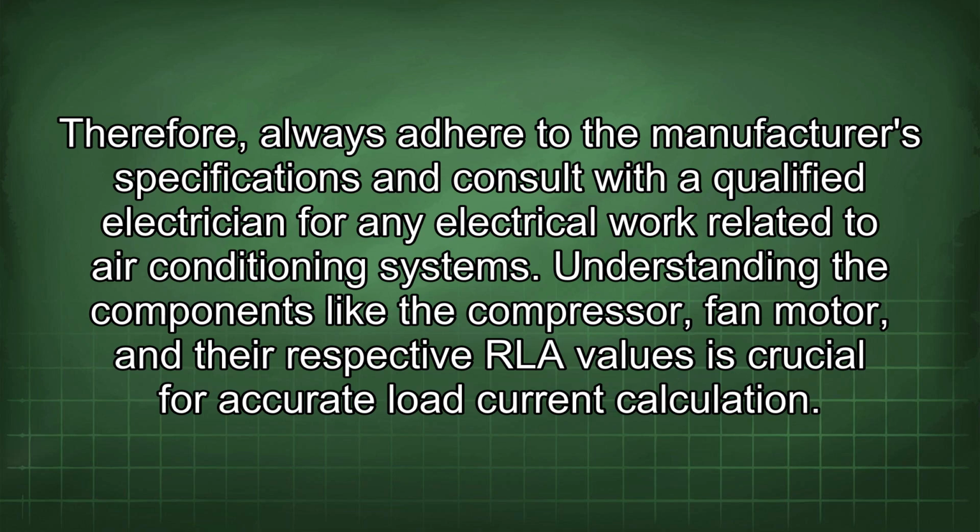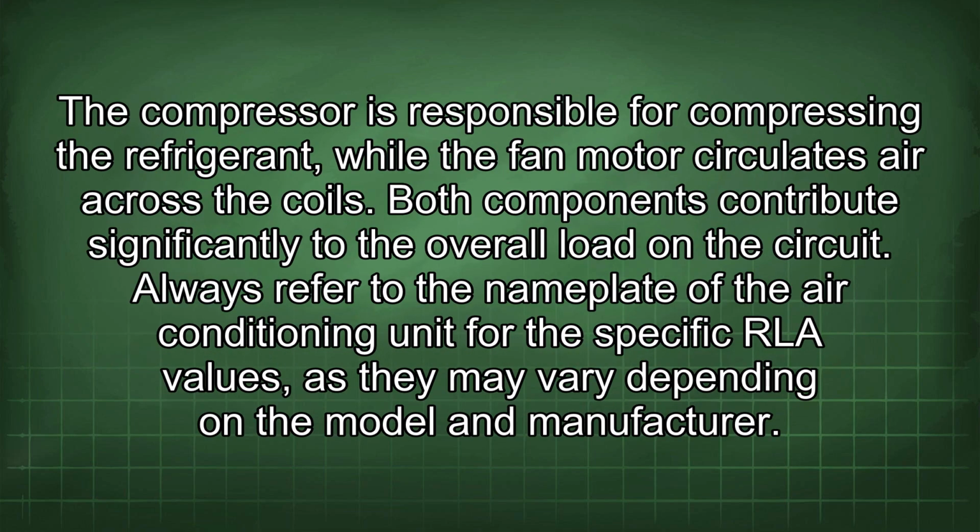current calculation. The compressor is responsible for compressing the refrigerant while the fan motor circulates air across the coils. Both components contribute significantly to the overall load on the circuit. Always refer to the nameplate of the air conditioning unit for the specific RLA values, as they may vary depending on the model and manufacturer.